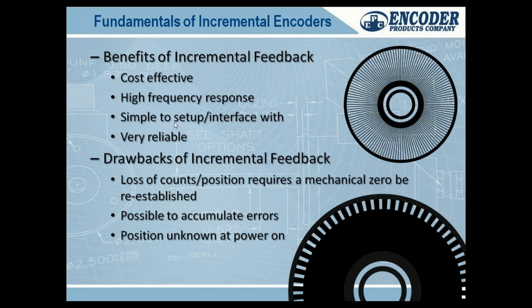They're very simple to set up. AB channels have been around, like I said, for over 50 years, decades, and most devices accept, you'll see quadrature, differential, all the different ways to say it, they will accept incremental signals. So it's very easy to set up and find a device that'll take it. They're incredibly reliable. The failure is the bearings. That's your biggest point of failure, those bearings going bad, or disk crashes if you're modular.